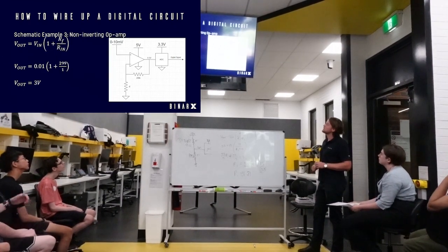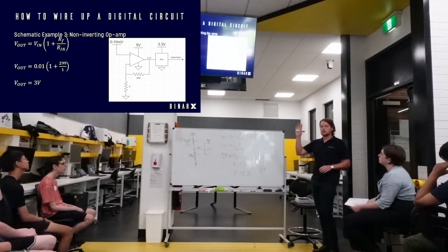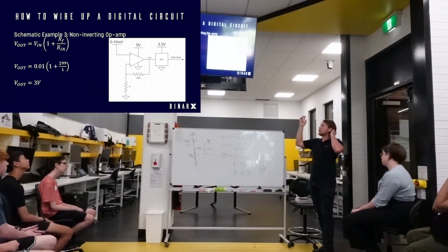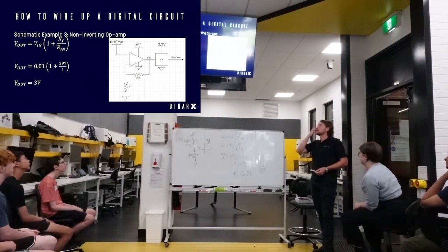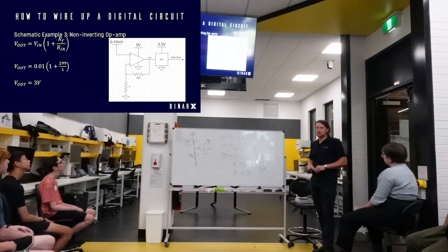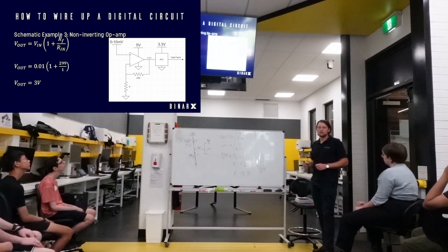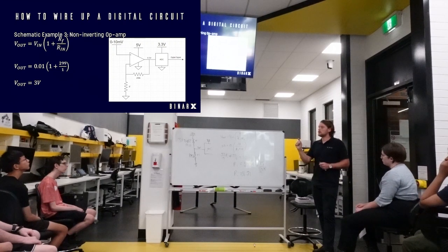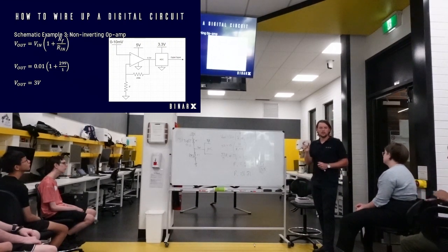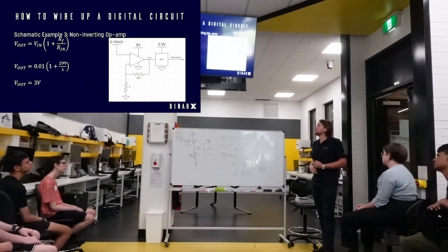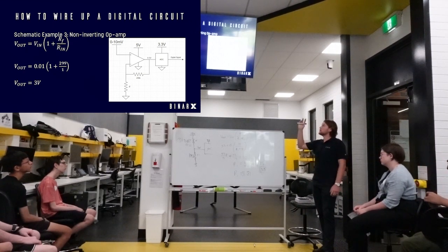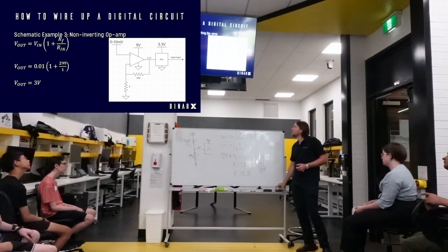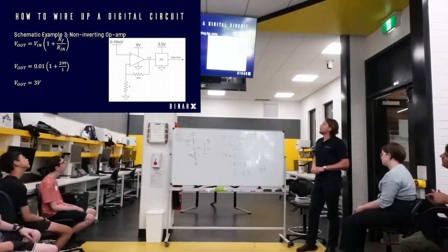All right, this is the next one that Jacob wanted me to go through, which is essentially the same problem, but instead of us having a really big signal that we're trying to read into our ADC, we're trying to amplify a really small signal into our ADC. So the 0 to 10 millivolt signal that you see there is not an exact number, but it's common if you have a temperature sensor that has a low reading input signal, a pressure sensor as well. You can get very small voltage changes across your sensor, which can tell you your pressure. So you need to amplify your really small signals into a really big signal so that you can read them in your 3.3 volt logic circuit. Okay?